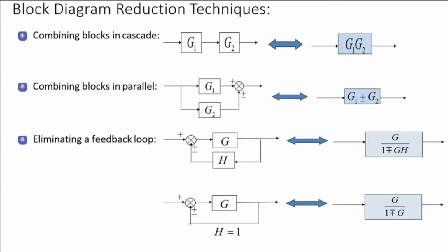Now, in order to merge these different blocks, what we need to do is combine these small blocks, and there are some standard ways of combining them. This is all what we call control system tradecraft. Control system engineers have devised these ways, and these are standard symbols that are used, so please use this symbol. G1 means the transfer function of the block containing G1, then this is G2. In the feedback direction we use the term H. So these are just standard ways of writing a control system.